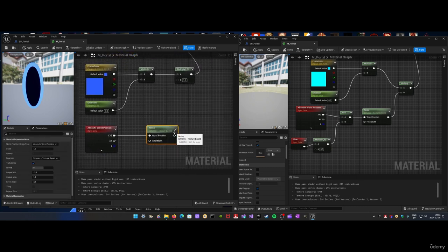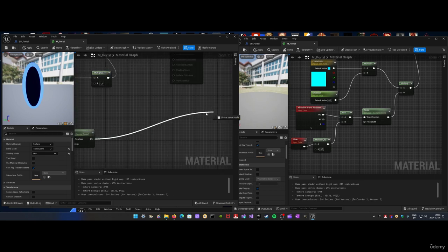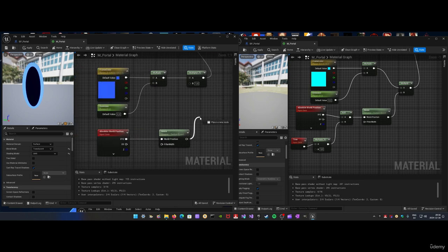First off, let's just connect this to the multiply node here because we want to combine this with the frame color. In other words, I want to affect the blue colored frame here with the noise effect, so I'm multiplying it with this node here. That's the good thing with multiplication, you're combining two effects together. So I'm combining the entire color here together with the noise effect.